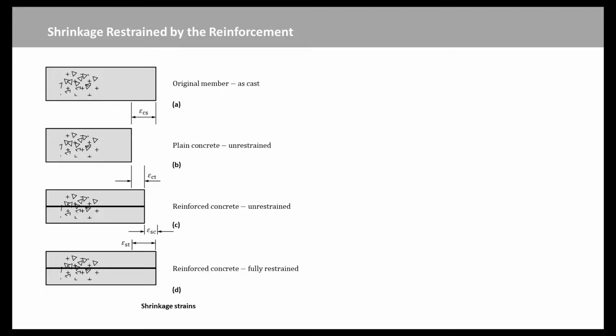During the setting process, the hydration of the cement causes a great deal of heat to be generated, and as the concrete cools, further shrinkage takes place as a result of thermal contraction. Even after the concrete has hardened, shrinkage continues as drying out persists over many months, and any subsequent wetting and drying can also cause swelling and shrinkage. If the change in volume of the concrete is allowed to take place freely and without restraint, there will be no stress change within the concrete. Restraint of the shrinkage, on the other hand, will cause tensile stresses.